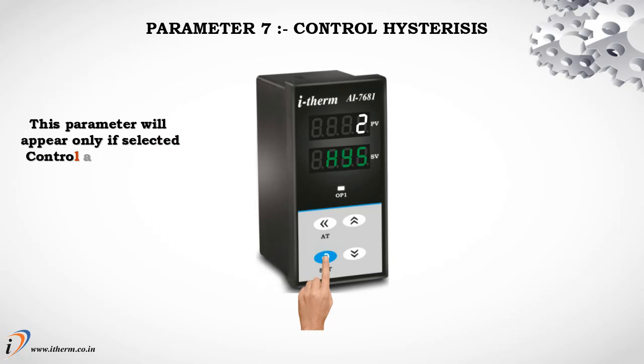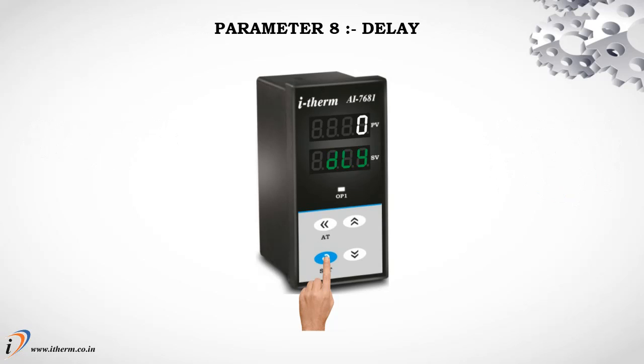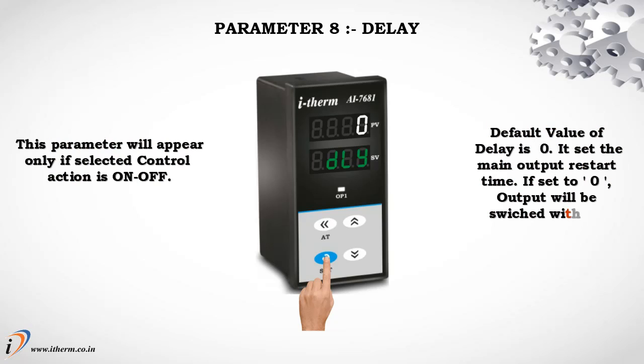Parameter 7, control hysteresis. This parameter will appear only if selected control action is on/off. Default value of hysteresis is 2 degrees centigrade. It sets the dead band between on and off switching of the output. Parameter 8, delay. This parameter will appear only if selected control action is on/off. Default value of delay is 0. It sets the main output restart time. If set to 0, output will be switched without delay.